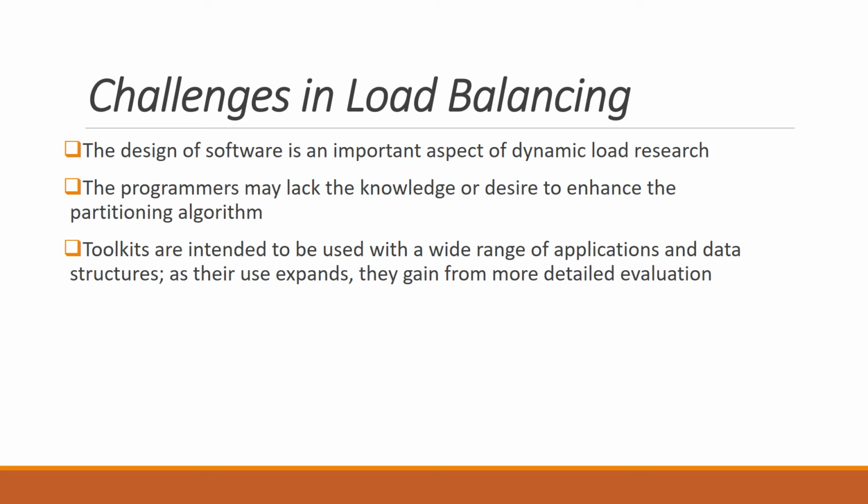There have been numerous strategies developed for static and dynamic load balancing, such as recursive bisection, space filling curve partitioning, and graph partitioning methods. These techniques provide useful splitting for a wide range of applications, implying that the load balancing problem has been solved. Crash, particle, and adaptive finite element simulations all use RB and SFC methods. Because of high quality serial and parallel graph partitioners, graph partitioning is useful in conventional adaptive and continuous finite difference simulations.